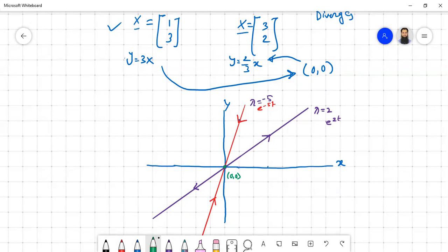We are interested in a small perturbation about the origin. So what will happen then? If you have a small perturbation along this axis, along the red axis, you are somewhere here. Again, it will come back to the same point. Again, if you have some perturbation, you are here, and again it will go back to the origin. Okay. But if you have some perturbation along this purple line, so now you're here, you will not come back to the origin; rather the direction here is this, so you'll diverge away. Similarly, if you're somewhere here, your system will be diverging away.